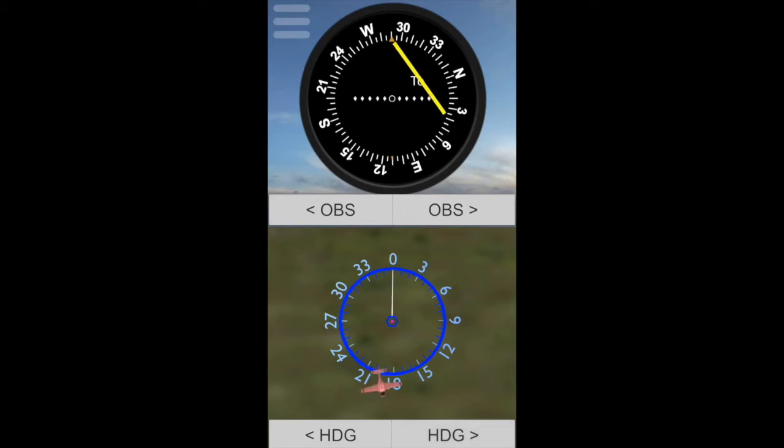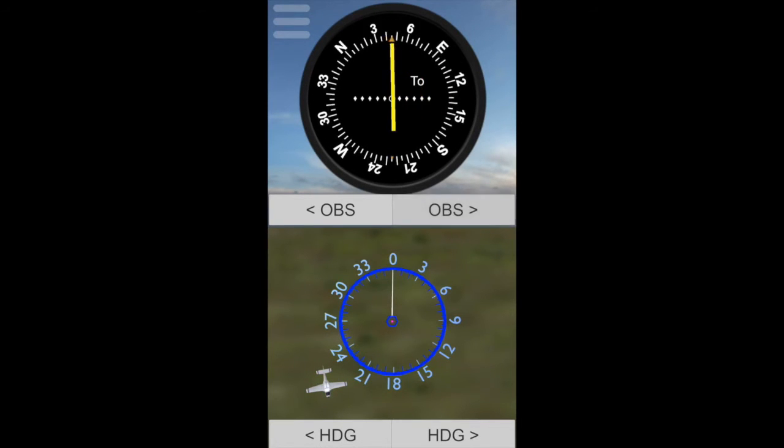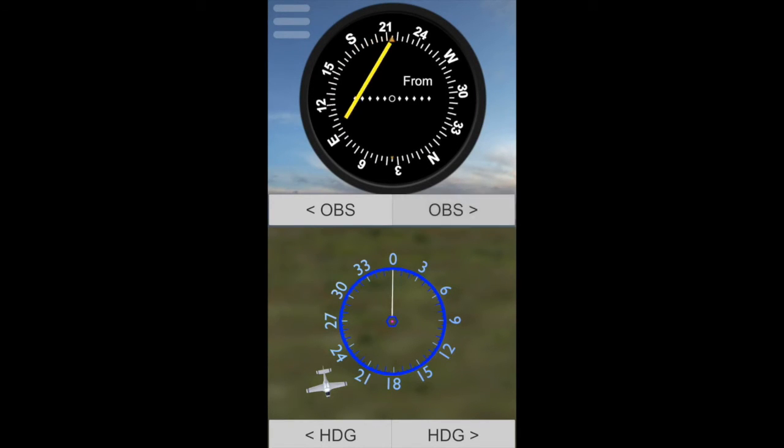You are flying, and if you want to use a VOR and find out where you are with respect to that VOR, you keep turning. Just put the plane anywhere. Put it here, for example. Turn the OBS, keep turning the OBS until I get a FROM indication. A FROM, and the needle is centered. I think this looks like 225.